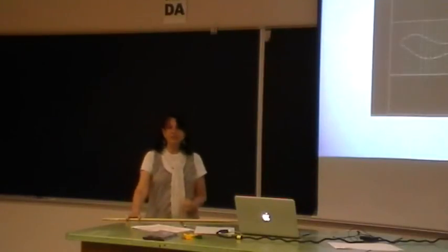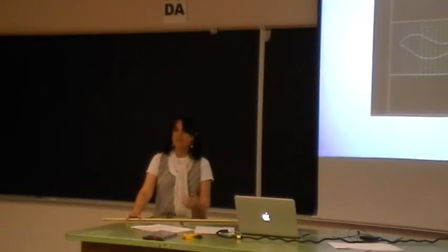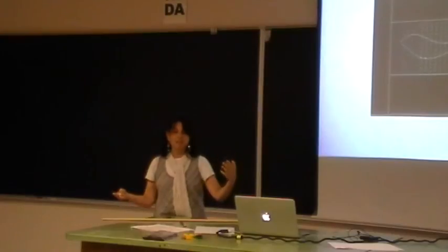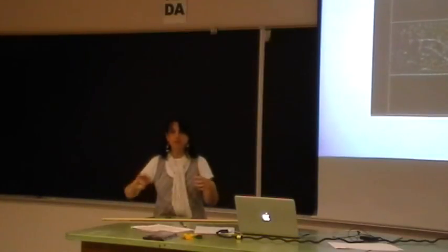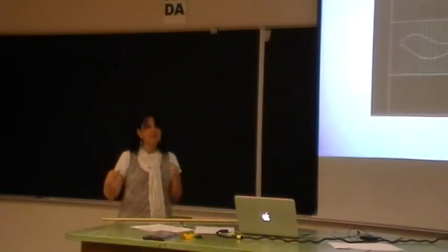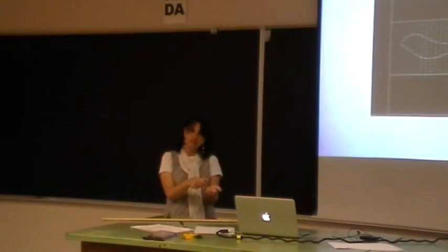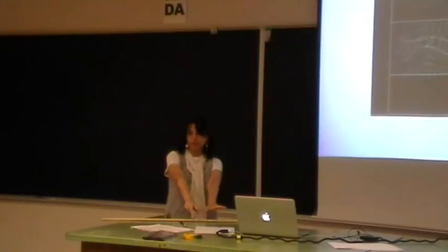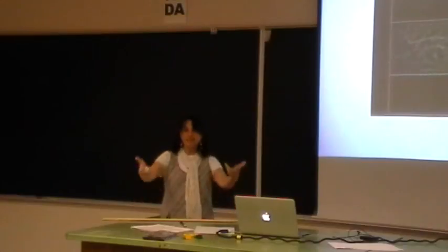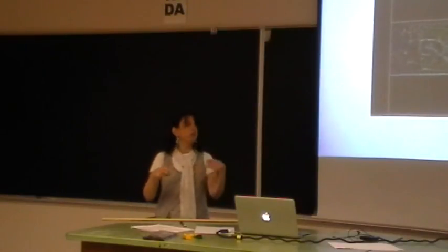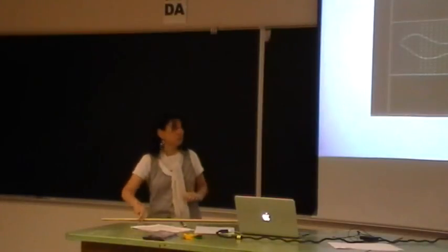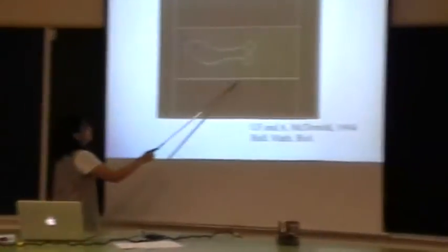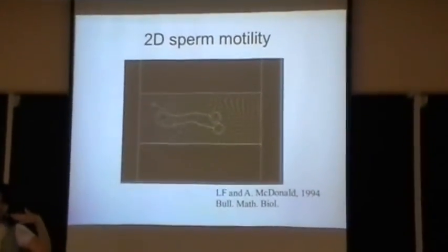Now, if the only force was the gradient of this energy function, and there was no fluid anywhere, the motion would minimize the energy and we would have the precise shape that we think we're prescribing. In fact, this is coupled completely with the fluid dynamics. So we have a force coming from this energy that's being spread to the fluid. The fluid then is responding in its velocity field, and we are moving these structures in that velocity field. So these two structures are being actuated. I should also say that we are representing elastic walls here, they're pretty rigid.